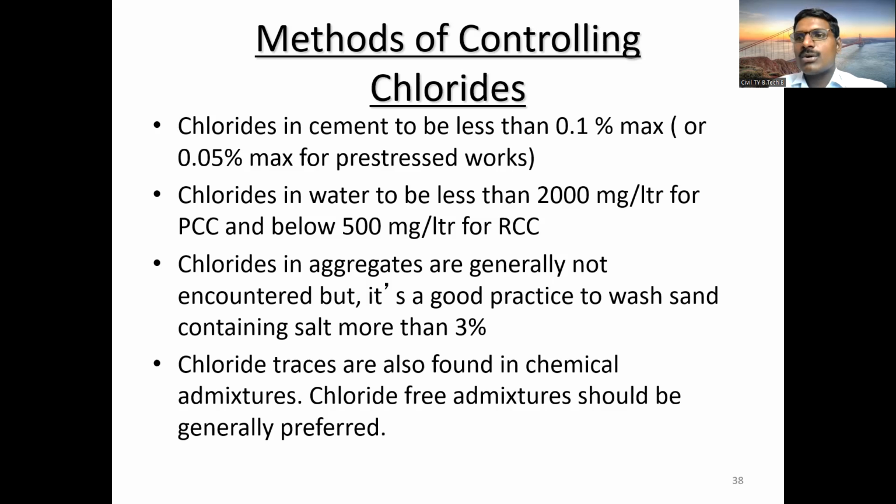Again, chloride in the aggregates is generally not encouraged, but it's a good practice to wash sand containing salts more than 3%.